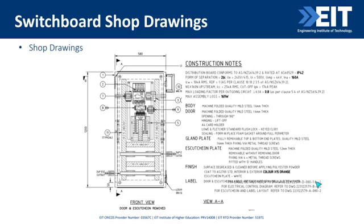And your shop drawing might look something like this. It takes that information and gives you a 600 by 1.2 meter distribution board. There's our isolator, there's our 24 pole chassis. We have some surge diverters and some section for controls. And then over here, we have that construction info, IP rating, form, amperage. So all of this, we're cross-checking against that single line diagram.